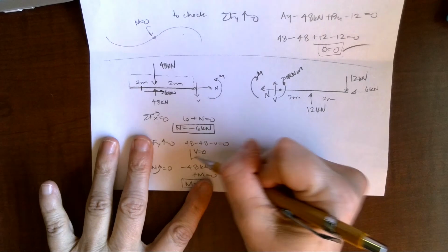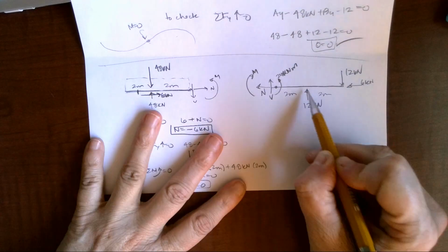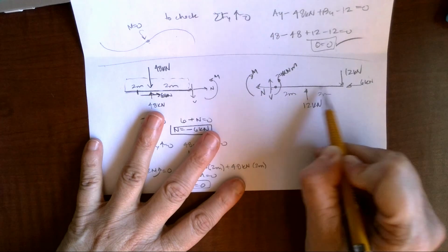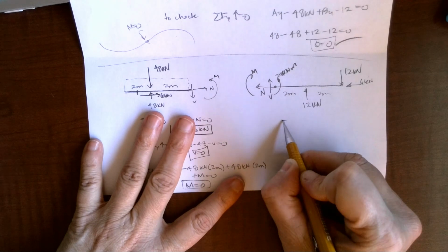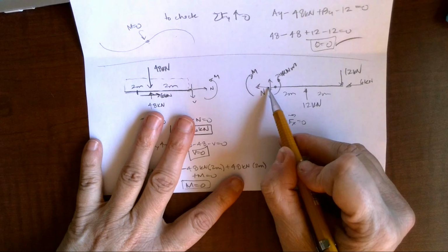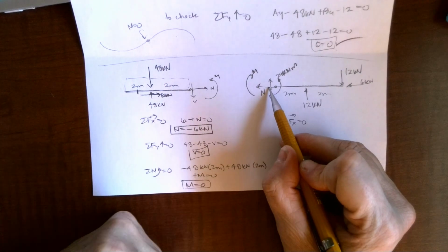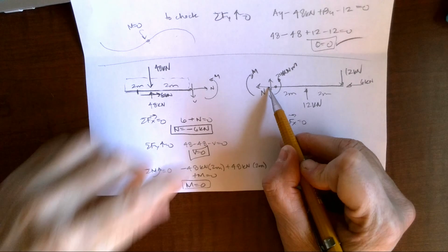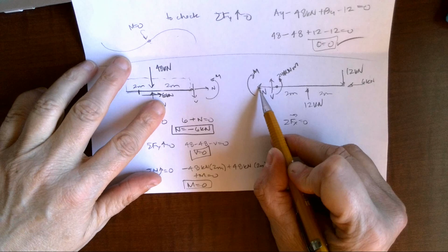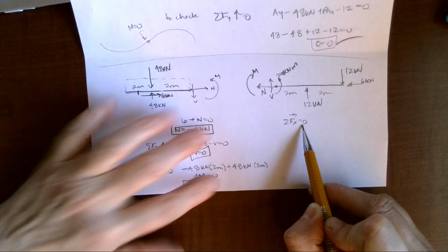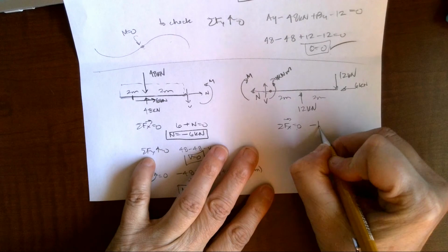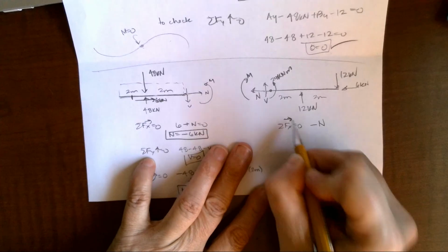I am going to start at the left side of my beam and move to the right. And I'm going to sum forces in the x direction. They equal 0. Now, I'm assuming positive normal force. Normal force is that perpendicular force to our cross section. I'm assuming it's in tension, I'm assuming it's a tension member. But when I make my sign convention for summing forces, it's a negative because it's going opposite of the direction I'm assuming to call positive.